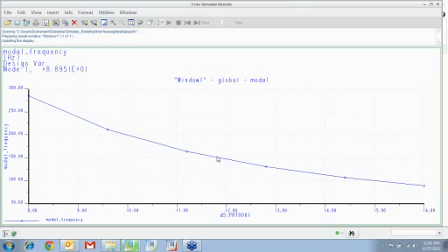So what should be the range of the variable that I have to change? I can change the variable from 11 to 11.5 to 12. It's between these two values. Now you see the advantage of a global sensitivity is it will tell you where your answer is. You run the optimization to confirm it.